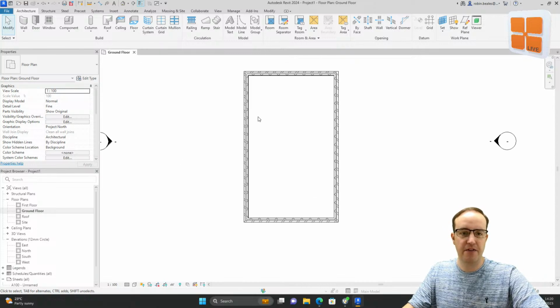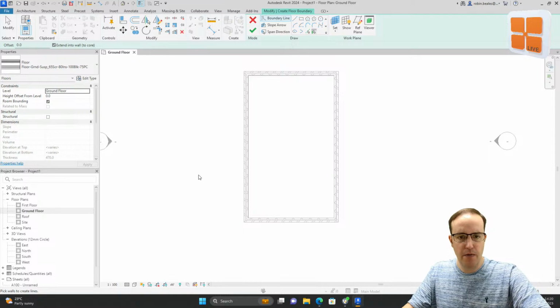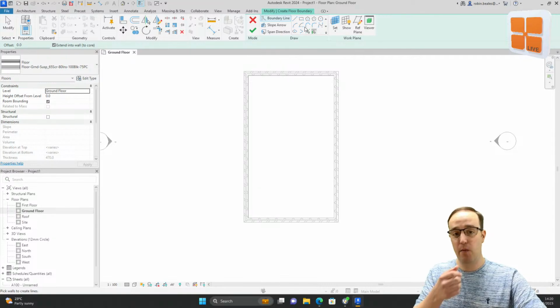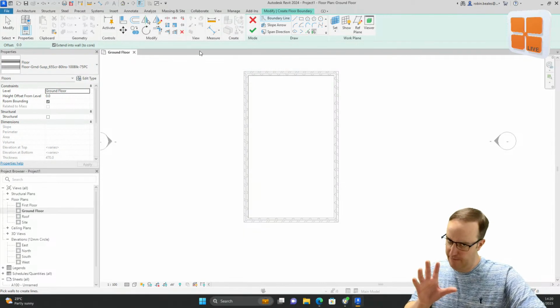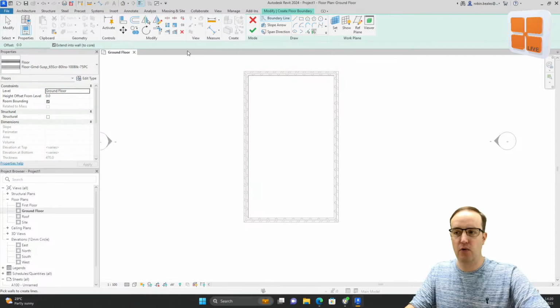The next thing I'm going to do is just draw some internal partitions. Or maybe I'll draw a floor first. Let's do a floor. So let's go to the floor tool. On the floor tool, we've, again, much like drawing these walls, have got lines, arcs, circles and squares. And actually, when you're drawing or placing anything, what I failed to point out when drawing the wall, it's very familiar to AutoCAD, the offset tool, the trim tool. They work in exactly the same way, give or take, as they do inside of AutoCAD.